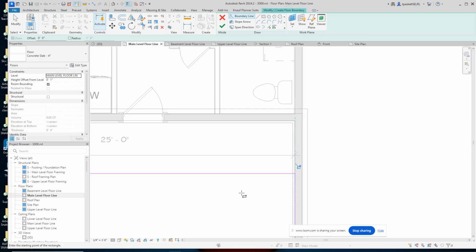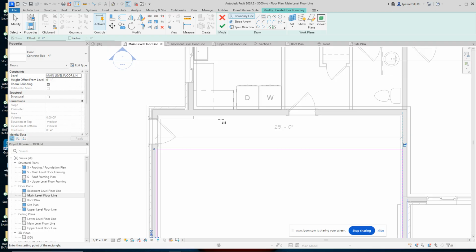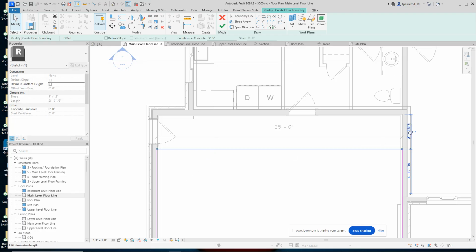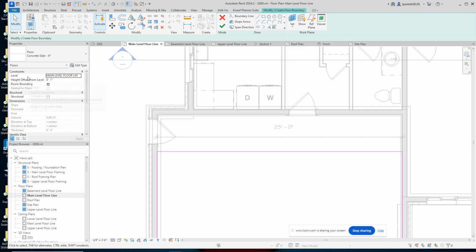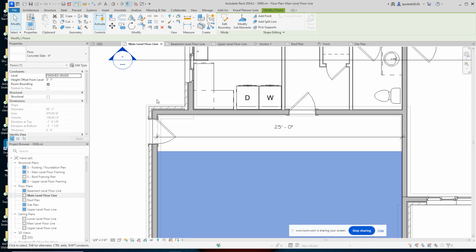And now we're going to give it a size. So the distance from the back of the garage to this line, we're going to size. So do modify. Select that back line. And make this value from wall to the edge 4 feet. Just 4 and enter. And that should be sufficient for what we need right now. Okay. And then when you come back over to our properties, set that to be at the finish grade, +1, and apply it. Then just check it off for right now. Okay. Just check it off, and so it's all done.